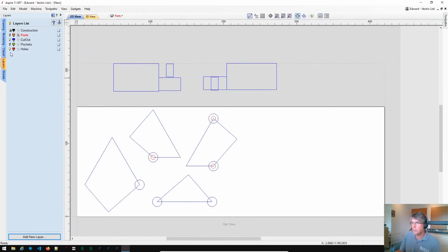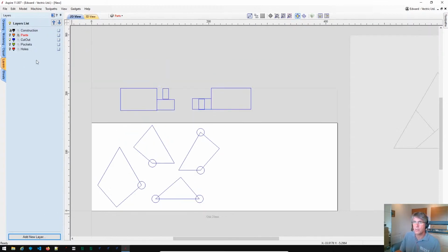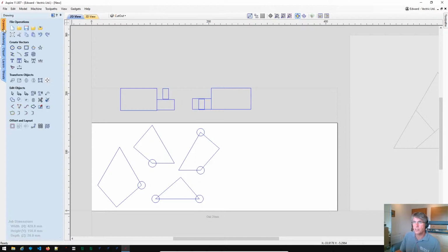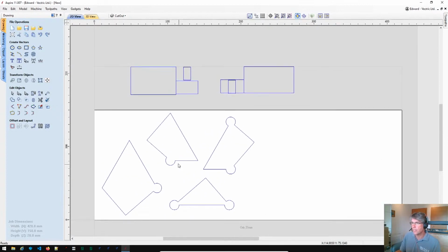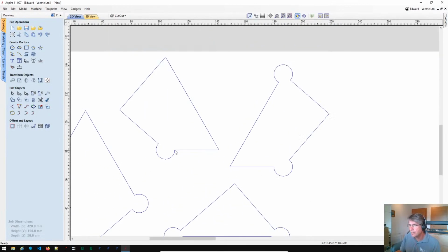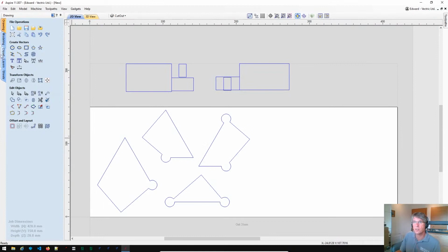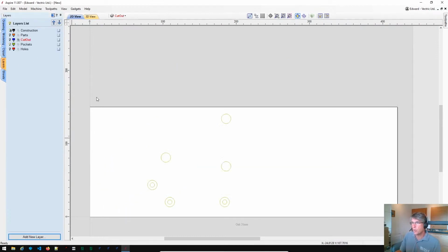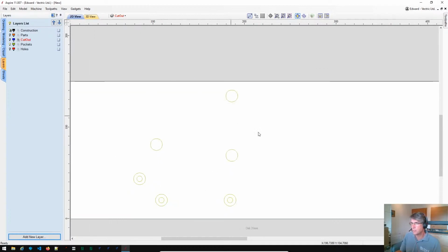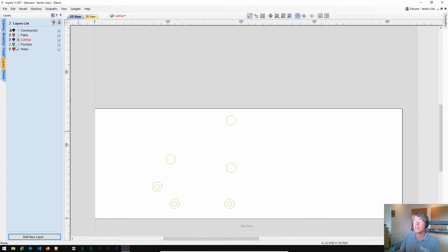So we've got a cutout path, which is just the external shapes. If we select that cutout, go into the drawing now, I can just select all those and say, give me the external outline of those. That's actually the cutout path we're going to want. We will come back and have a little chat about filleting in a minute. I mustn't forget that, because there is a filleting issue, depending on our tool geometry, when we come to machine it. But let's go back to the layers. So that's the cutout. That looks pretty good. Pockets seem pretty straightforward, so that's what we're going to come down and pocket in between. And then there's the holes, which are just literally the drill holes.